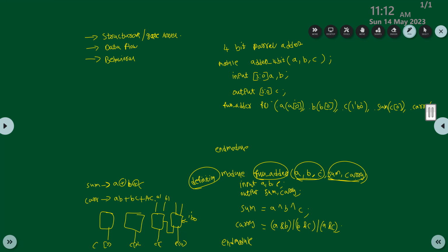So you have to declare a wire, of this 1, 2, 3 wires are fine. Wire [2:0], which is for carry. And remember one thing, you can use the same names in both modules, so there is no overlapping error kind of thing.